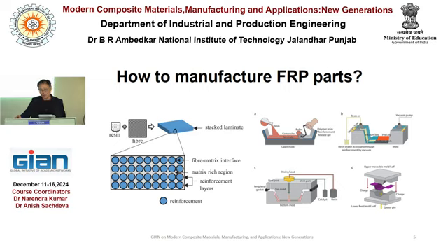We make an open mold, and on it resin is prepared. On that, the fiber will be distributed, and in this case multiple layers can be prepared like this. Then after that, it is cured by using a vacuum pack or a top mold sometimes, or hot pressing.